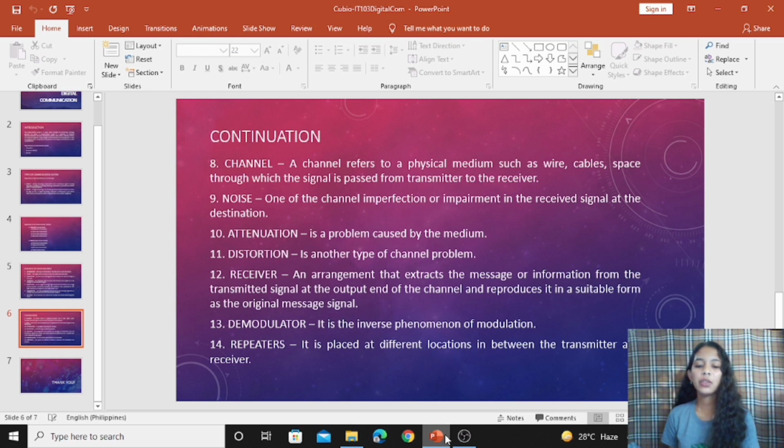The external sources include interference from nearby transmitted signals, interference generated by natural source such as lightning, solar or cosmic radiation, from automobile generated radiation, and etc. The internal noise can be minimized and eliminated by appropriate design of the channel, shielding of cables. Also by the digital transmission, external noise can be much minimized.